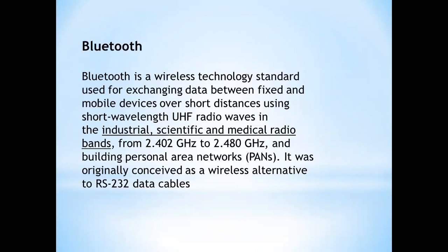Since Bluetooth is a short range, limited speed and low power technology, it is less attractive to corporate wireless local area networks that are generally powered with the 802.11 wireless LAN technologies. Each Bluetooth-enabled device contains a transceiver chip operating in the ISM, that is industrial, scientific and medical, radio frequency band of 2.4 GHz to 2.48 GHz. This frequency is generally available worldwide for free without any licensing restriction. The ISM band is divided into 79 channels, each carrying a bandwidth of 1 MHz.